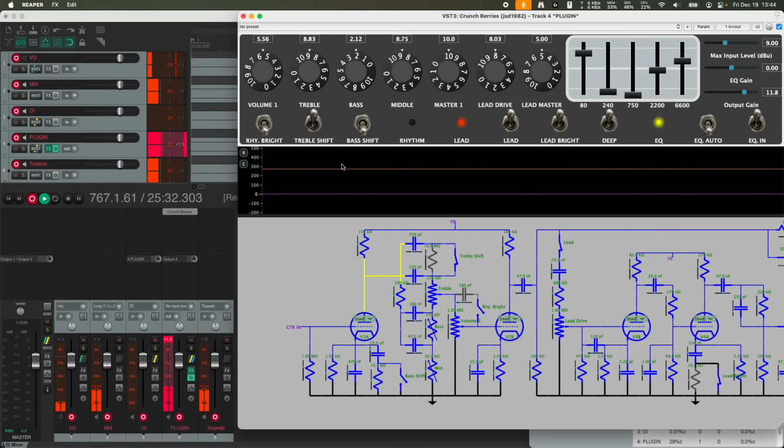So this new color up here is actually what the guitar signal is being amplified up to, coming out of the plate of the first tube stage. And then from there, once you run it through a simple filter network, everything comes down to the 0 level. So it's got this 300-ish volt DC offset up here. You just run it through any capacitor of any kind, and that'll pretty much drop it down to the 0 volt. So it'll remove that DC offset.